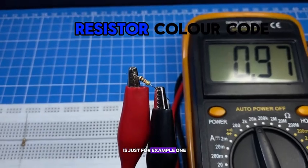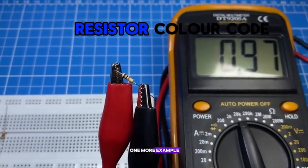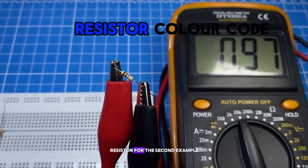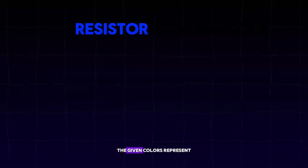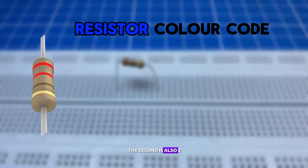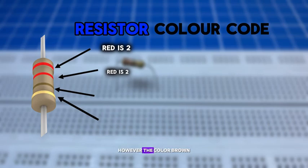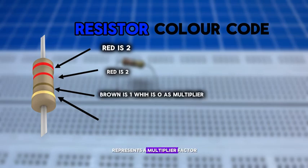This is just example 1, and for you to better understand it yourself, I will show you one more example. So let's use this resistor for the second example. The given colors represent digit 2, which is red, and the second is also 2, which is also red. The third band is a multiplier band. The color brown represents a multiplier factor, and brown is 1, which is 0 in multiplier.